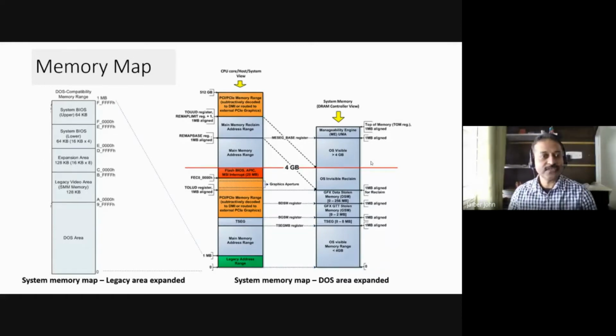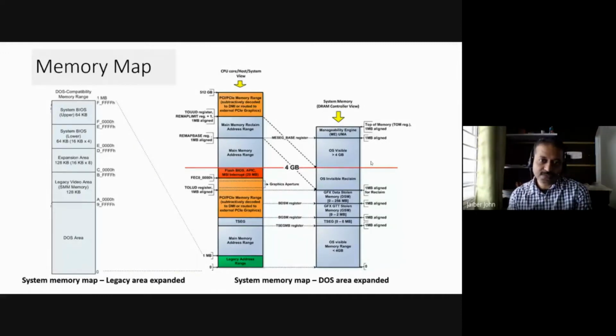But in reality, the addressable space in memory is not contiguous, and there are n number of partitions in it. So this depends on each architecture. Here I'm showing a typical modern x86 memory map. And if you're an embedded programmer or RTOS engineer, or device driver developer, for example, this is something which we have to really look at, because we can't just use any memory location randomly. They're all predefined for certain use.